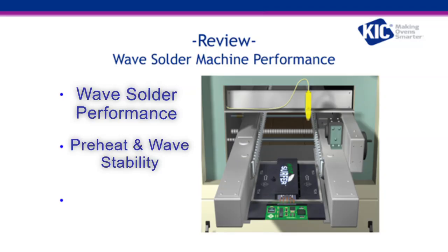Confirm preheat and wave stability. The Wave Surfer captures the actual temperatures achieved during the preheat stage and records the behavior of the chip wave and main wave. By analyzing these graphs, you can verify whether the PCB reaches the correct thermal soak, ensure that the wave is stable, and confirm there are no fluctuations that could cause solder defects.